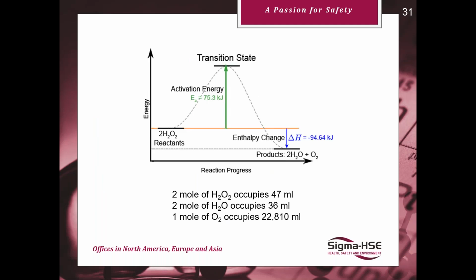So just to highlight again why pressure is so paramount in chemical reaction hazard analysis, we can look at this simple example whereby we supply energy to hydrogen peroxide to yield the decomposition products water and oxygen. So we can see here that the volume of each constituent takes up these volumes at atmospheric pressure. And if we were to confine this reaction to, say, a 1 litre vessel, initially at standard temperatures and pressures, the resultant pressure post-reaction would be approximately 362 psi. So you can see how that can be quite a dangerous hazard if not accounted for.